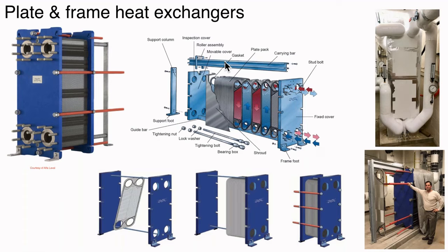That's a lot of work. We don't want to be in a position where we have to disassemble something like this on an annual basis to clean it. We want to deal with the dirt issue a different way. We want to collect the dirt before it goes into the heat exchanger. But if necessary, they can be disassembled, whereas a brazed plate, you can't do that.